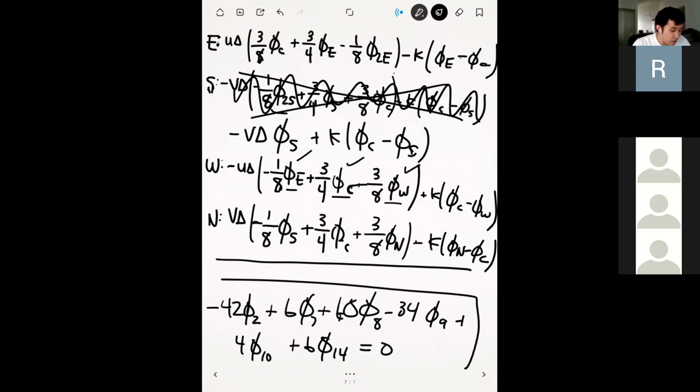And then for each integral, you need to check just like we did here: do we have ourselves, do we have a neighbor to the east, and do we have a neighbor two to the east? And if not, then you need to replace that expression with the basic upwinding scheme. Cell 29 is on the top right, so it's the opposite of that one, so the decisions that you make based on QUICK will be a little bit different.